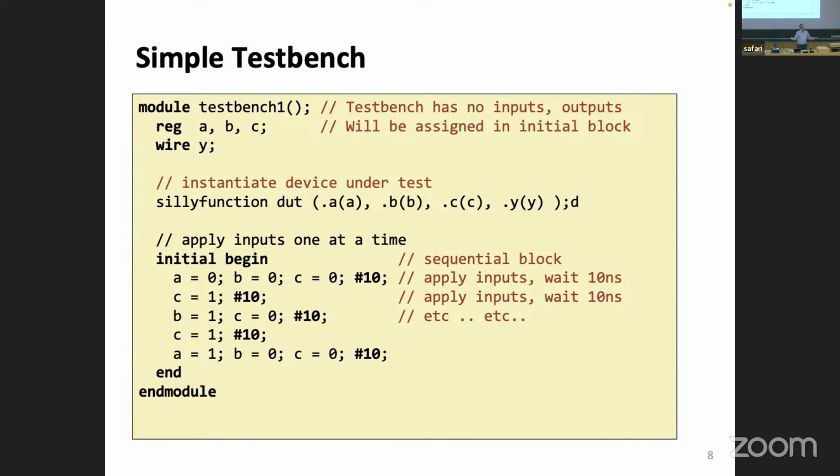So, normally, we had this always block, and the always block triggered at certain instances. And once it triggered, we know that it was meant as, how shall I say, as a virtual loop. Anytime the inputs changed or the conditions changed, it would trigger, but it wouldn't be executed on the program. It's just like telling the synthesizer what kind of circuit you wanted. And then you made all these assignments, and you could use cool things like if, then, else, case, and it looked great, right?